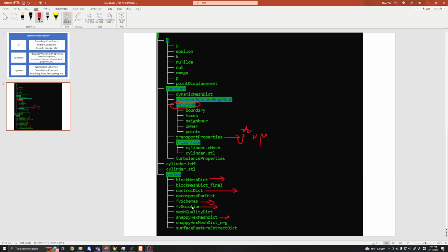So in other words, we can set up the linear solvers, matrix solvers, and we can set up the details of our solution algorithm. We can choose the SIMPLE algorithm or the PISO algorithm, and we can choose how many steps we want to use inside our SIMPLE algorithm, or whether we want to use relaxation factors etc. in this file. Okay,